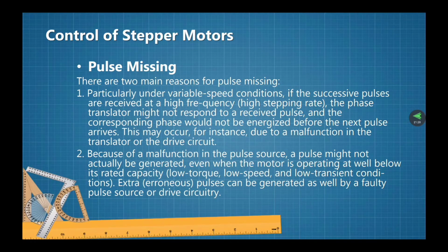Under relatively favorable condition, particularly with a small step angle, if a single pulse is missed, the motor will decelerate so that a complete cycle of the pulse is missed. Then it will lock in again with the input pulse sequence. In this case, the motor will trail the correct trajectory by the rotor teeth pitch angle theta r.